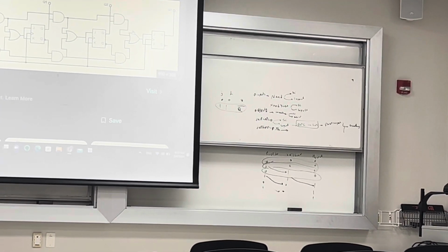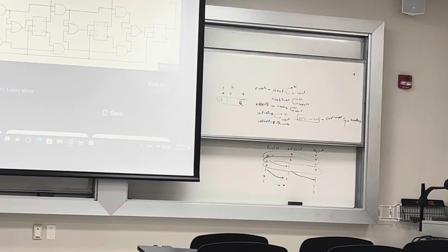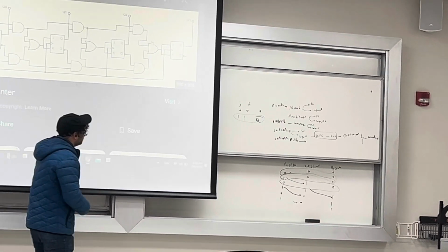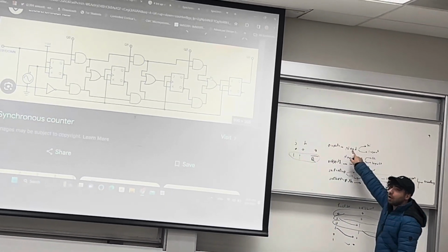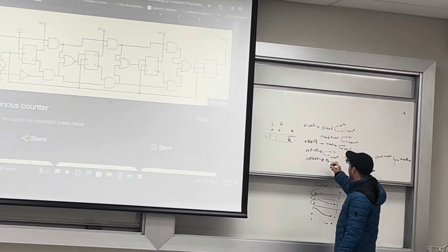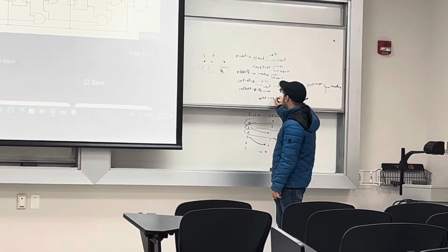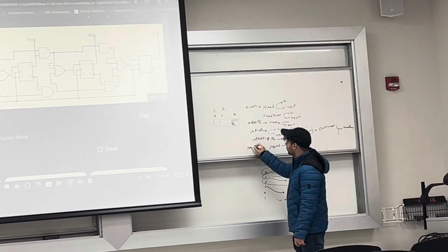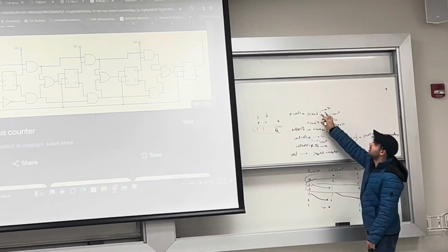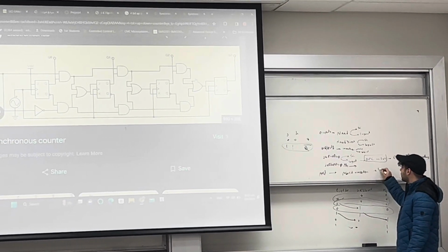After you design the JK flip-flop, you have the inverter again. You have the NAND and OR gate. As I think you designed the NAND gate, the only difference is that you put this NAND gate with one inverter at the end of that, and then design your AND gate. So for the AND gate, put this NAND gate from project 3 and put the inverter after that, and then design the schematic and layout.